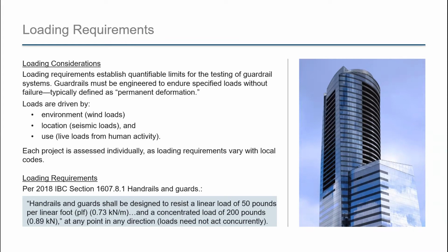And that's pretty important for railing design because there's a lot of railings used around terraces or on balconies. So those areas on the buildings are just as important as the other factors in determining the wind loads. There are some coastal locations, which some of you are familiar with, such as some jurisdictions in Florida, where windborne debris testing is required to make certain guardrails will remain in place after they are impacted by debris during hurricanes.